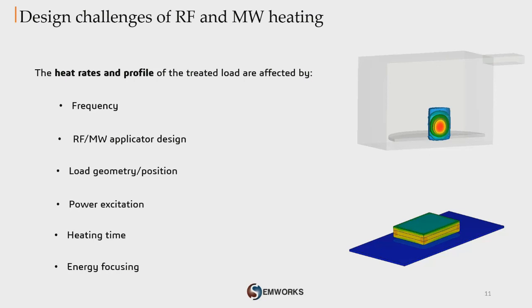We come now to our final factor, which is the energy focusing, which means the geometrical and process factors that allow to focus the maximum of lost power inside the heated sample and get more uniform heating profile. This factor includes the number of excited parts for multi-part configurations, as well as the excited phase and mode for each part. Let's check now with our studied example how this factor can affect the heated behavior.